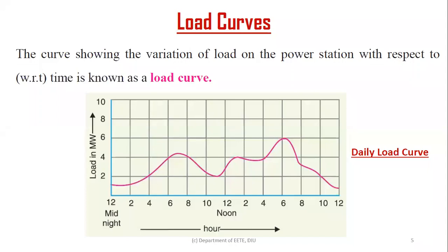So the load curve is very important because it gives us that scenario to see when the maximum load or the maximum demand is given, or when the less amount is given. One interesting thing I will discuss, very advanced, will be discussed later also: the load curve is very important for selecting the capacity of a power station.